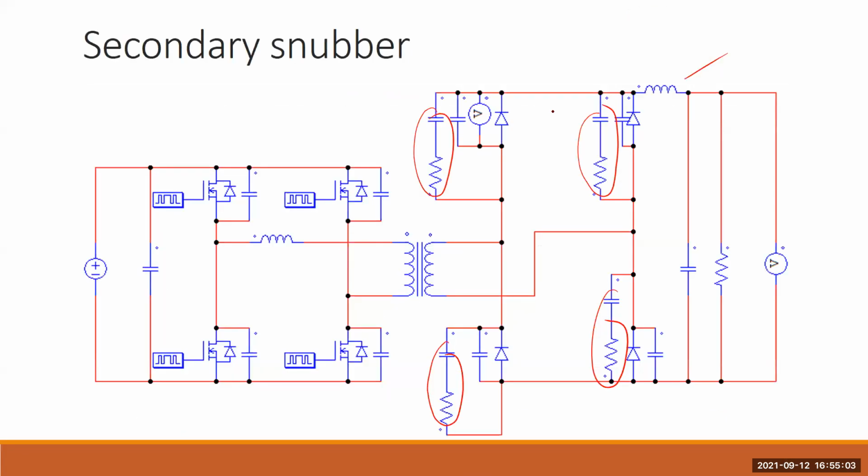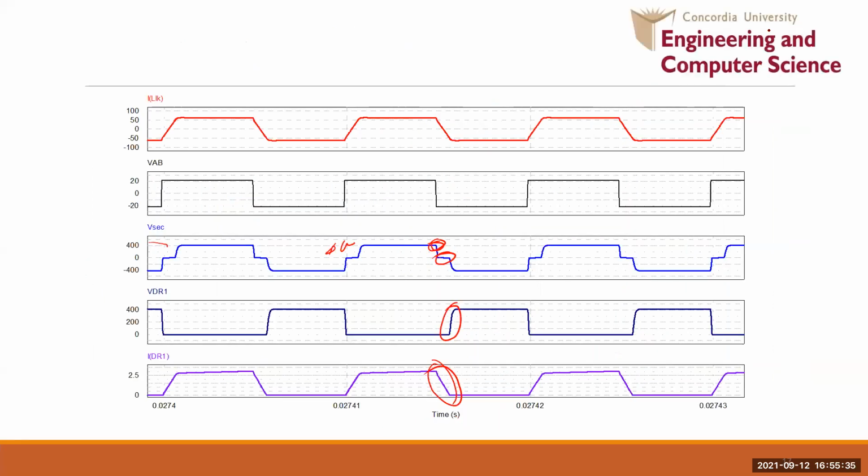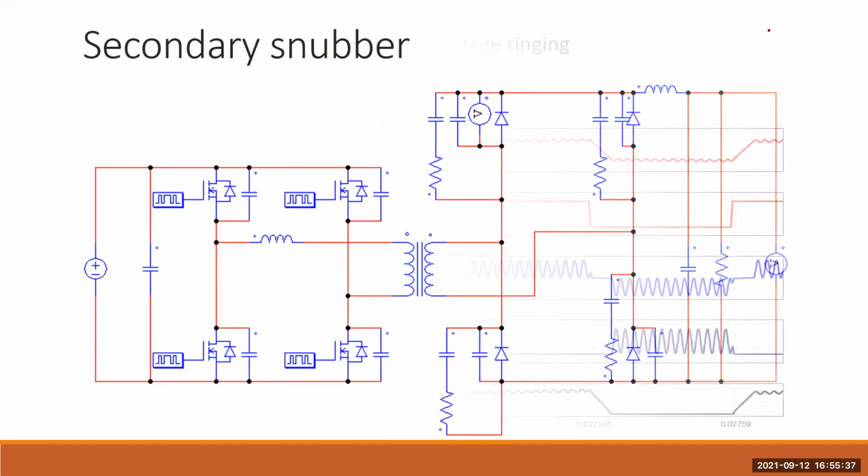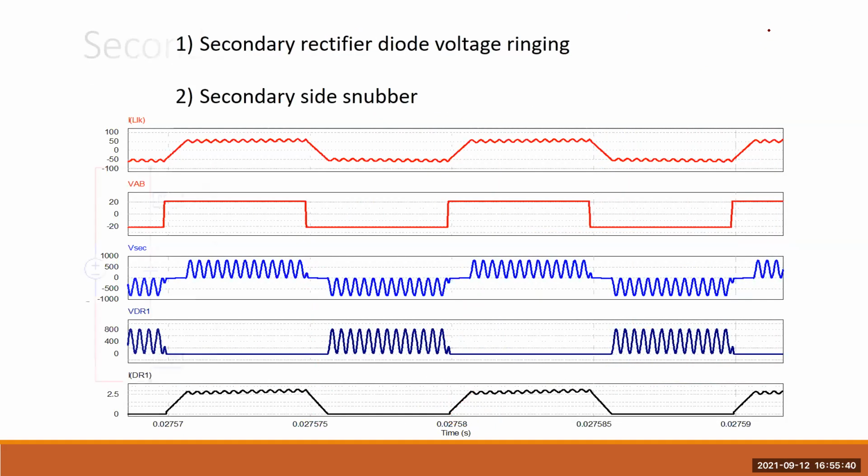Lossy solution means all the four diodes are conducting, they are causing losses instead of two diodes conducting before. And now this RC snubber, so this resistance, the energy is circulating through that, the resonant energy. So that is dissipated in these resistances. So very easily 2 to 3% efficiency loss happens. But you see the snubber effect, how it was before, how it is now.